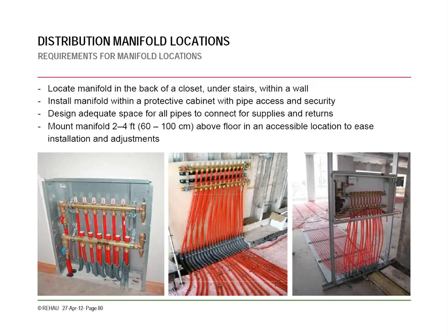These are some larger ones. The one on the left here is just a 6-loop manifold, but these other two are quite large. They look like 10-loop manifolds. So you just have to be cognizant of where you're putting them. You have to have access to them.